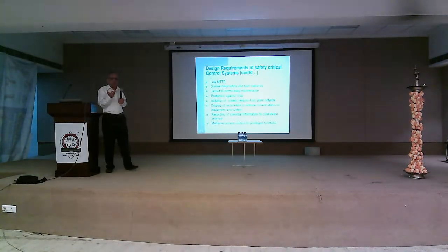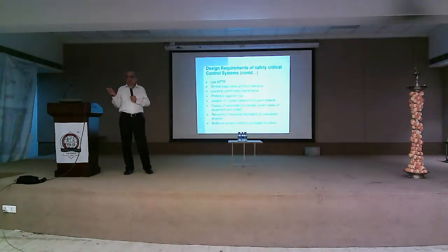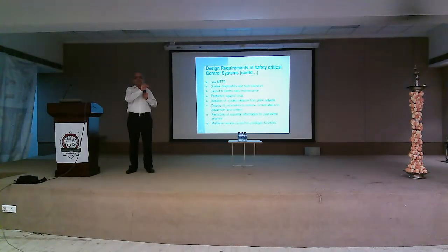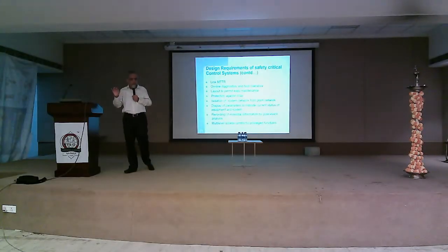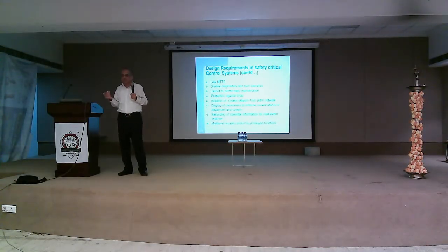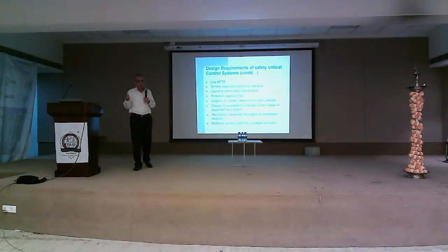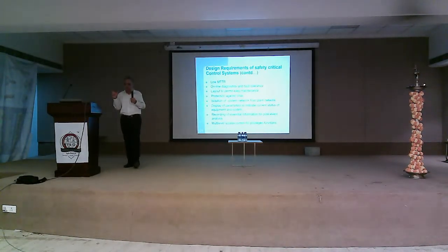Now what is online diagnosis? For example, if it is an ADC, then you must see that the ADC is working properly. For that you have a zero input as well as a fixed reference IC, and you see that it remains linear. For digital input, we use what is called finite impulse testing (FIT). Through software, temporarily we change the input and see whether it is really changing or not. That's called finite impulse testing, which is done during the diagnostic cycle.